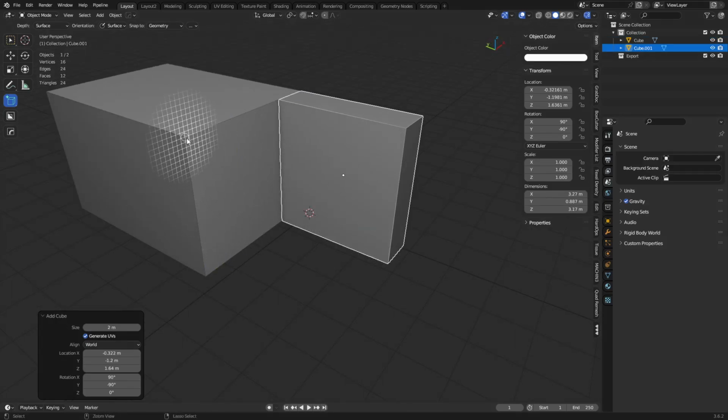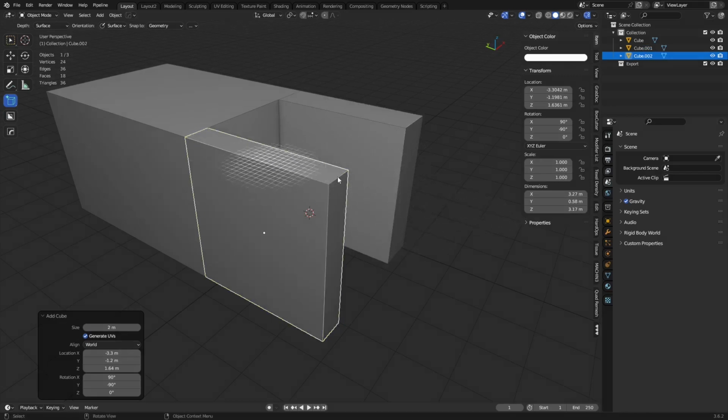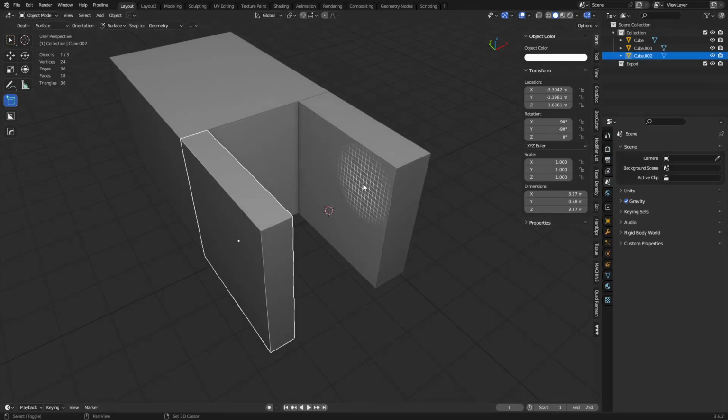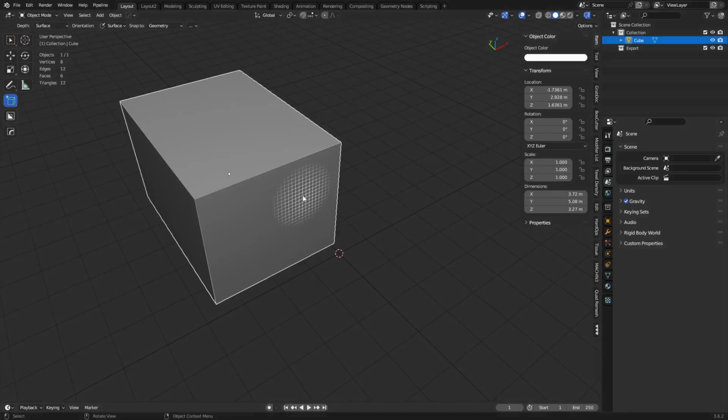Let's say we do that same thing over here. Try it one more time. Is it messed up? But anyways, if we hold down Control the whole time, we can actually snap to this edge, so it'll be the same distance out. The only thing is it's not on the grid yet, but we want it on the grid because that's the best way to block things out when you're trying to create modular environments, right? And so we can do that.